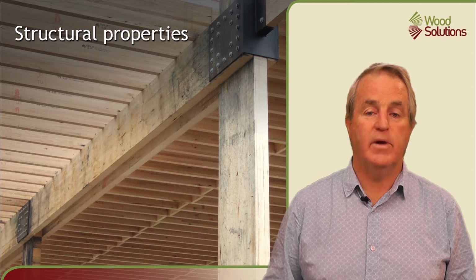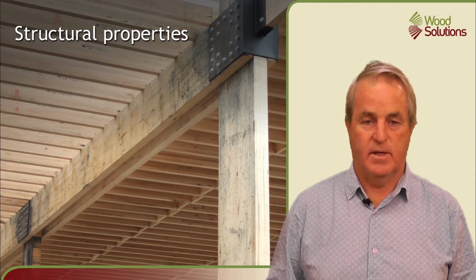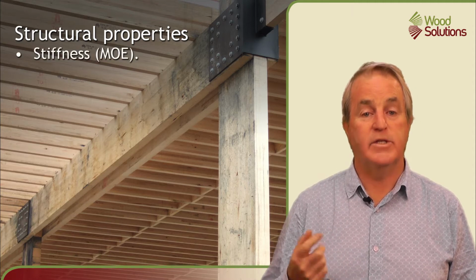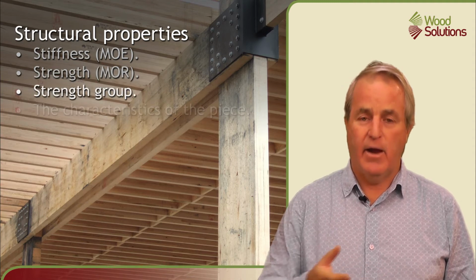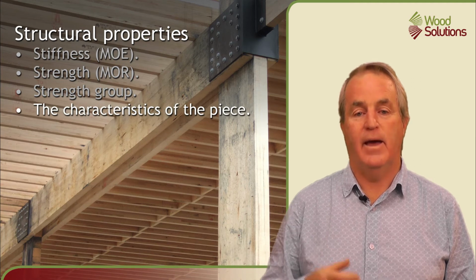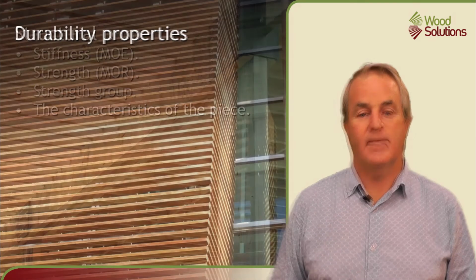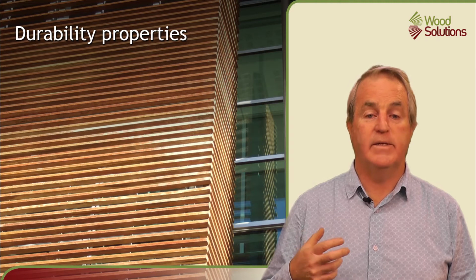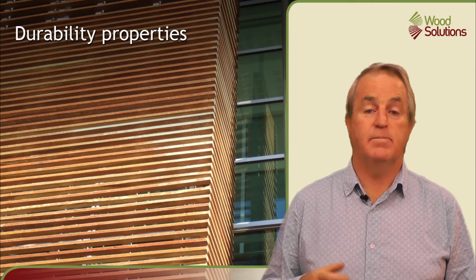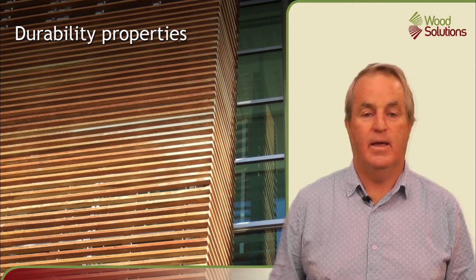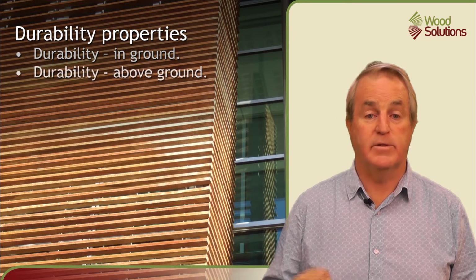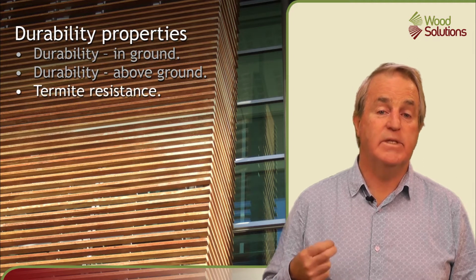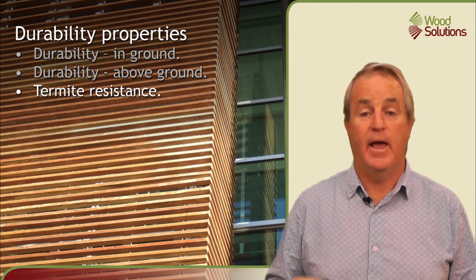Then there are properties that relate to timber's structural performance, such as its stiffness or its strength, or the strength group of species, and the characteristics of the piece and how they influence strength. Then there are properties that relate to timber's durability when exposed to environmental hazards, such as its durability when placed in the ground or exposed above ground, and its resistance to attack from termites and its liquid susceptibility.